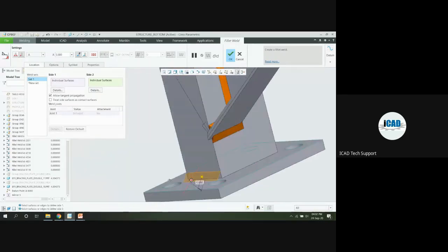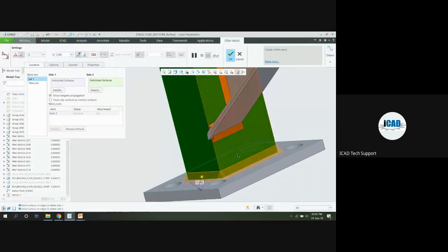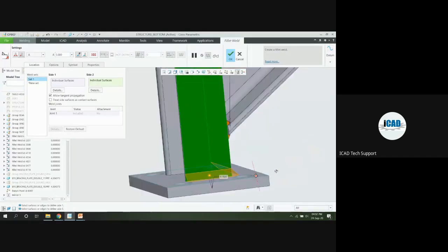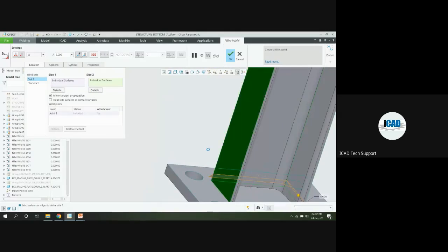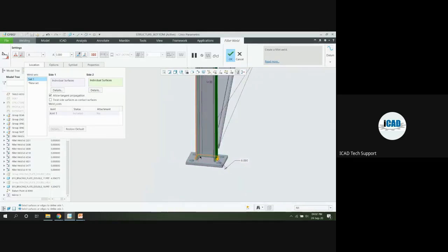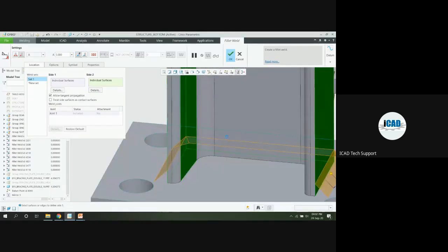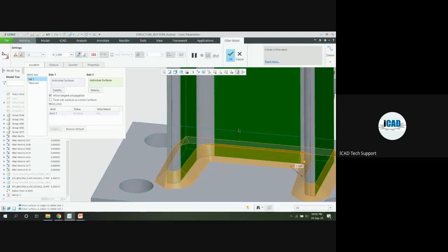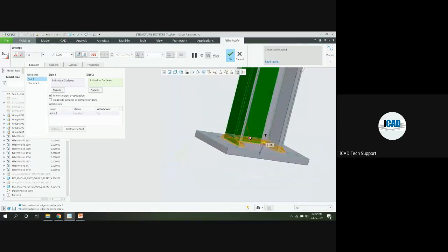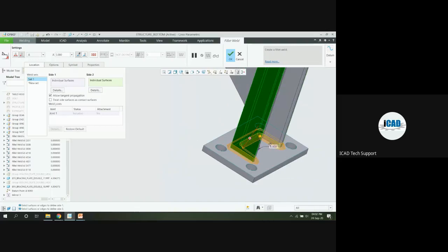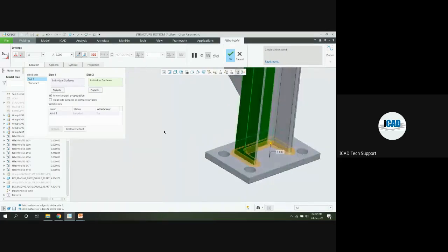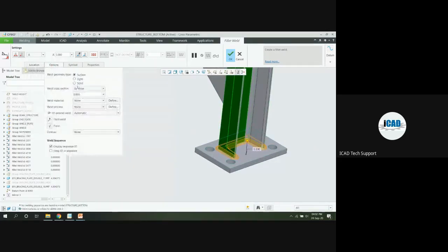Now you can see, if I am pressing the Control button while selecting side two, here I am selecting side 2, side 3, and the internal surfaces. Now you can see all the loop gets automatically completed. So this way we can show the weldings.